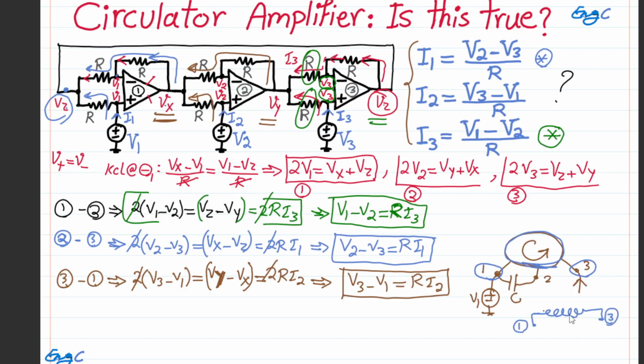So that's one of the practical ways to come up with a floating inductor. Floating meaning that the two nodes of the inductor are not connected to ground. It's floating between node 1 and 3. But this is a practical way, without having an inductor, from a capacitor effectively, coming up with a floating inductor. And that's really practically interesting. I will show this in a separate video. I hope that this is helpful.